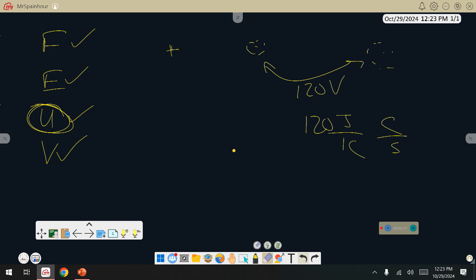This bad boy runs on 540 watts, which means 540 joules per second. Now we know that it's coming from that outlet over there, so we're getting 120 joules per coulomb, which means 1 coulomb is going to get me 120, 2 is going to get me 240, 3 is going to get me, of course, 360, and so on. I'm going to need about 4.5 coulombs per second running through this particular guy, and yes, that is actually relatively reasonable for an electronics thing of this particular size.